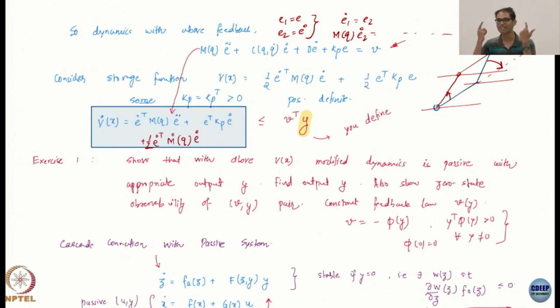In your head, if you think like that, it makes so much more sense. All I'm doing is giving it a spring connected to my waypoint and then to my quadrotor body, and it's just pulling it, so it will get to that point. Or you can think of it as a damped spring, so obviously it stays there. You pull it, then the next waypoint pulls it, and then the next waypoint pulls it. So this is exactly like that. I'm creating an artificial spring.